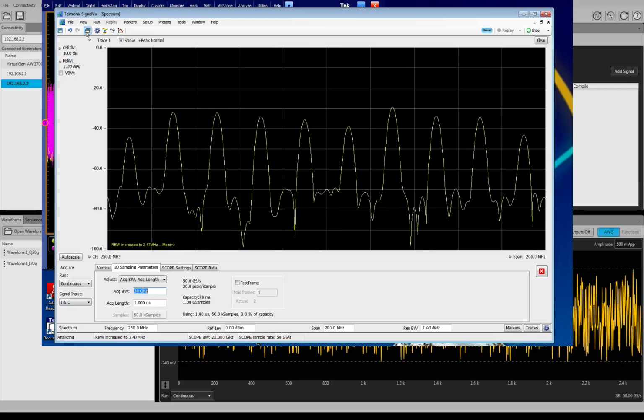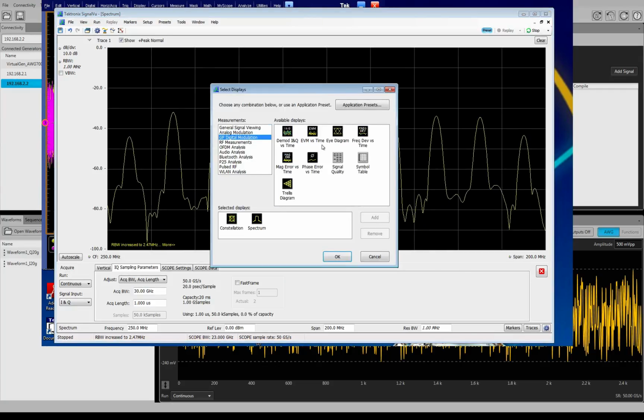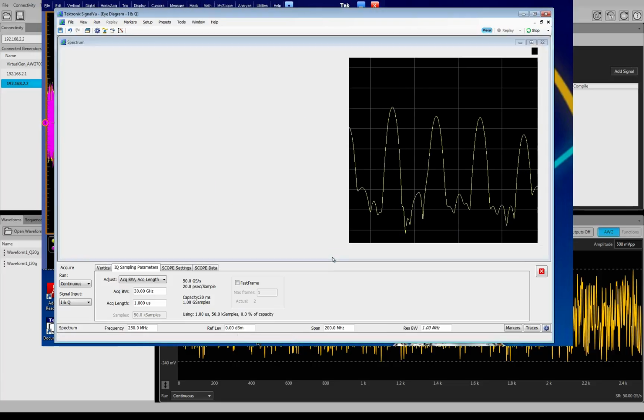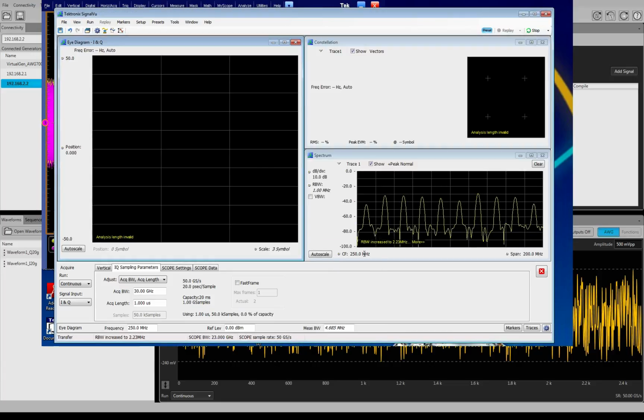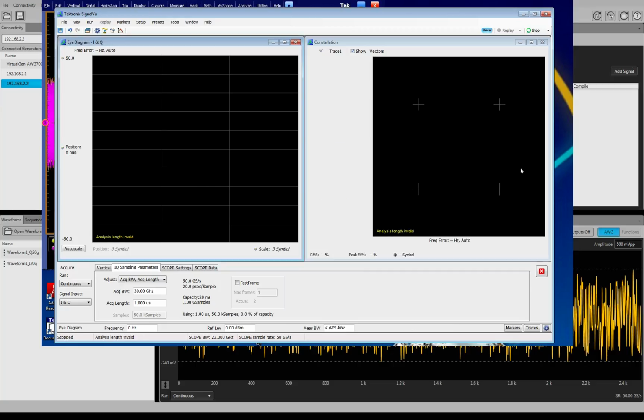And if you have seen my earlier videos, you know that we can go here, we go constellation, we go to I diagram. Just add it. For those interested, here we can look at the spectrum. As this is an IQ, we're going to look from negative to positive. So I go here and I set this up to center frequency 0 and a span maybe of 25 GHz, and you can see the spectrum. It's kind of useless anyway, so I remove that one.